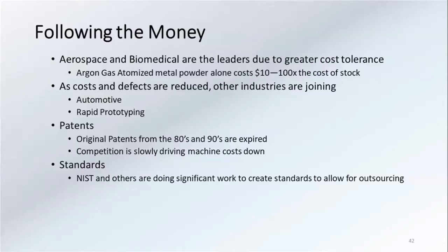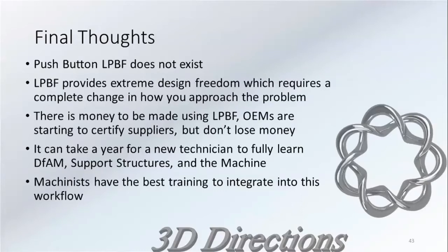So if you can do it traditionally, do it traditionally, but consider your low volume thresholds. If you're only building one, it might be cheaper to do laser powder bed fusion. If you're building several, it might not be. So final thoughts, push button laser powder bed fusion does not exist. It takes a while to learn the way to properly support a part. You get extreme design freedom, but it also comes with a lot of work involved.